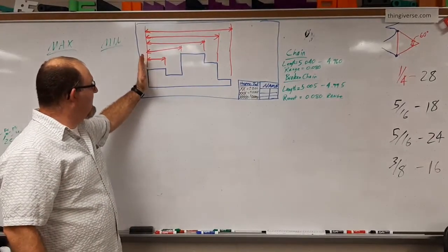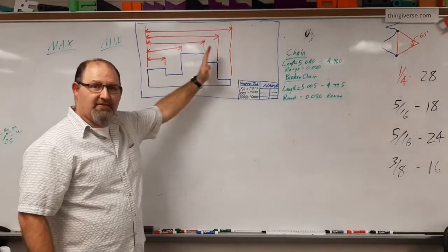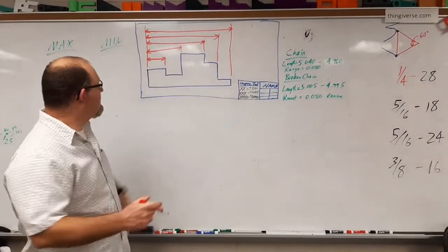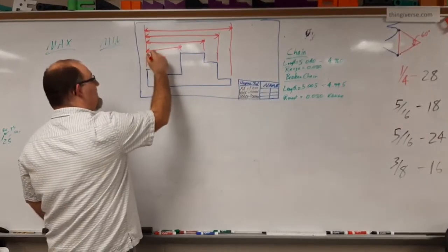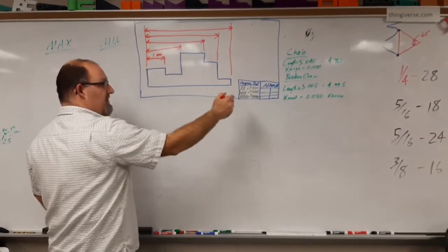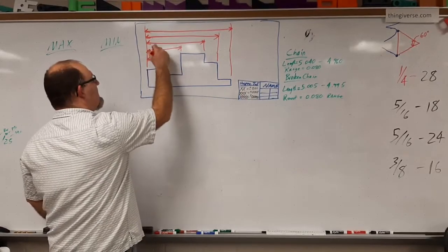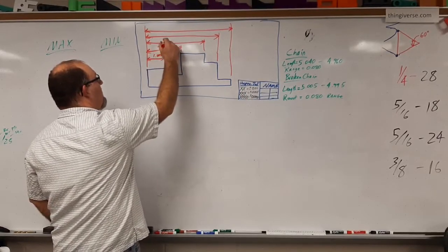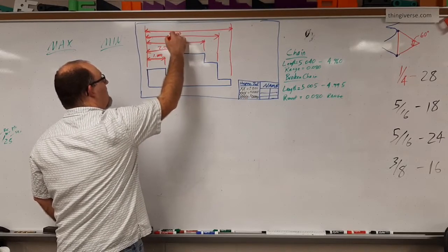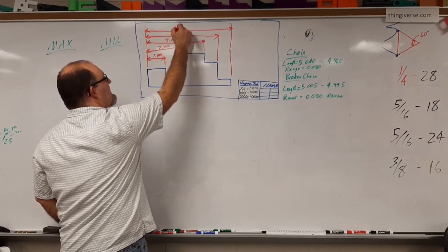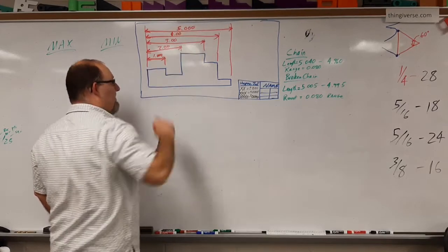This datum point here is what controls everything else. Okay, so in this case, keep using the same decimal numbers, 1.000, so that's still the plus or minus 5 thousandths. The next one here is 2.00, 3.00, 4.00, and then the top one here was 3 place decimals, 5.000.